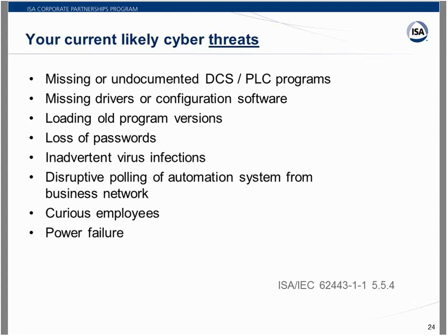So let me just show you an example of how I would mitigate a lost password, just as an aside. I would put the password actually in the cabinet, right there on the processor, right? So if you need access to that unit, the password's on the processor. I would also lock the door to the cabinet. I would put a tamper switch on the cabinet that opens and goes to the control room. So you have then a policy. It says anytime that panel is open, somebody has to call the control room first and they log access.